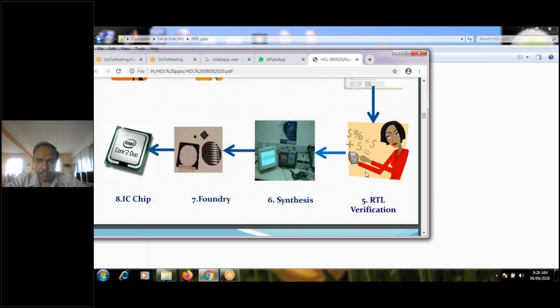Okay. So once the simulation part is clear, with the help of test bench waveform, you are checking the working of your AND gate, say, with respect to your truth table. In the test bench waveform, you are setting all the inputs. Say A and B are two inputs, you can set the inputs like 0, 0, 0, 1, 1, 0, 1, 1. Then you can generate the simulation model. If that simulator part is working, then the next part would be your synthesis part.